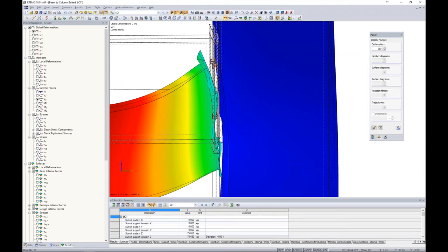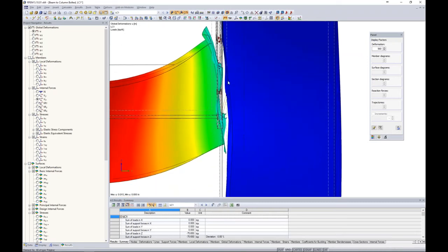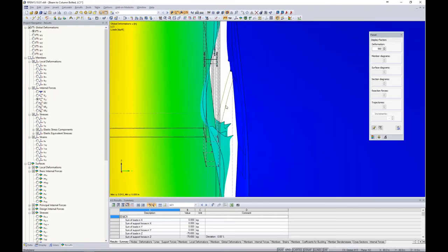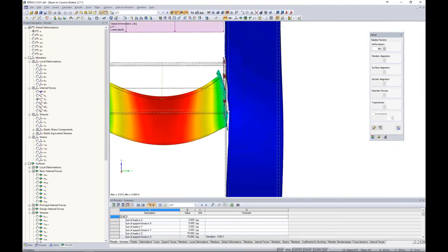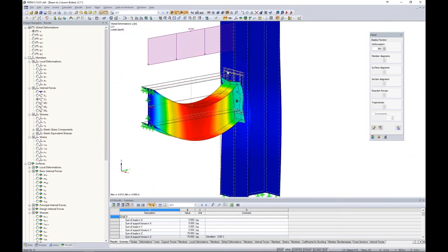As we move along the plate, places where there are compression forces, well, that's where we should see the full interaction between the 2 surface elements, or actually we have multiple surface elements for these contact solids now. Here are my bolts in tension, of course, as well. So same exact concept. The only thing that I did was split that contact solid into several simpler elements.